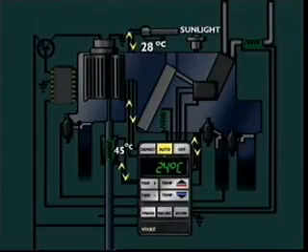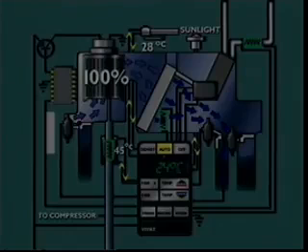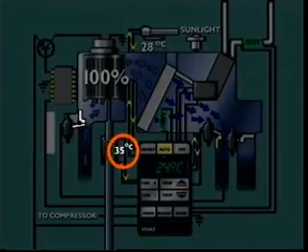When the engine has started and the climate control system is functioning, the electronic control unit switches on the air conditioning compressor and increases the speed of the interior ventilation fan. Air is drawn into the fan either from outside the vehicle or from within the cabin. The air then flows through the air conditioning evaporator core where heat is removed. The cold air-conditioned air is directed by flaps and ducts throughout the cabin of the vehicle, absorbing heat from the vehicle cabin and occupants and thus lowering the temperature.